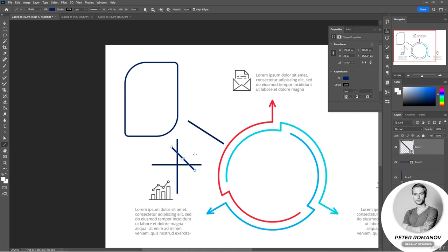You see the level under which this line is drawn, so I drew it. By the way, if you hold down Shift before drawing the shape, then all the shapes will be drawn on the same layer, which is what I have now. If I wanted these lines to be on different layers, I had to start drawing a little, and then press Shift. This way I would have a straight line. And look, it's already on a new layer. Now again, I have already started drawing a little bit by pressing Shift, and the line is on a new layer again. Here is a small nuance.